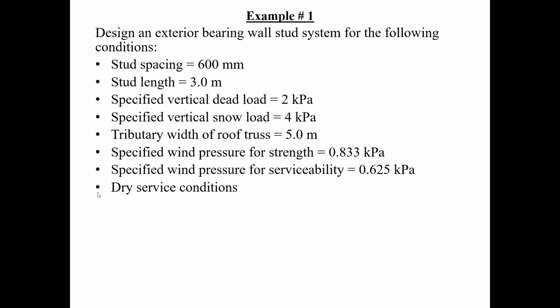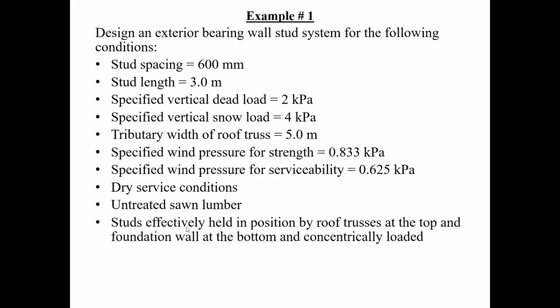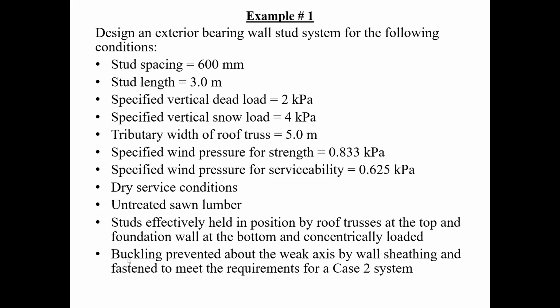So now we have, of course, dry service conditions because it's going to be a wall, and we have untreated lumber because we don't need to treat it. It's going to stay in a relatively good environment. Studs are effectively pinned by the roof truss and the foundations, and are concentrically loaded. That means the truss goes right over the top plate, and therefore you can consider it to be concentrically loaded. And buckling is prevented about the weak axis where the wall sheeting is fastened, meeting the class 2.